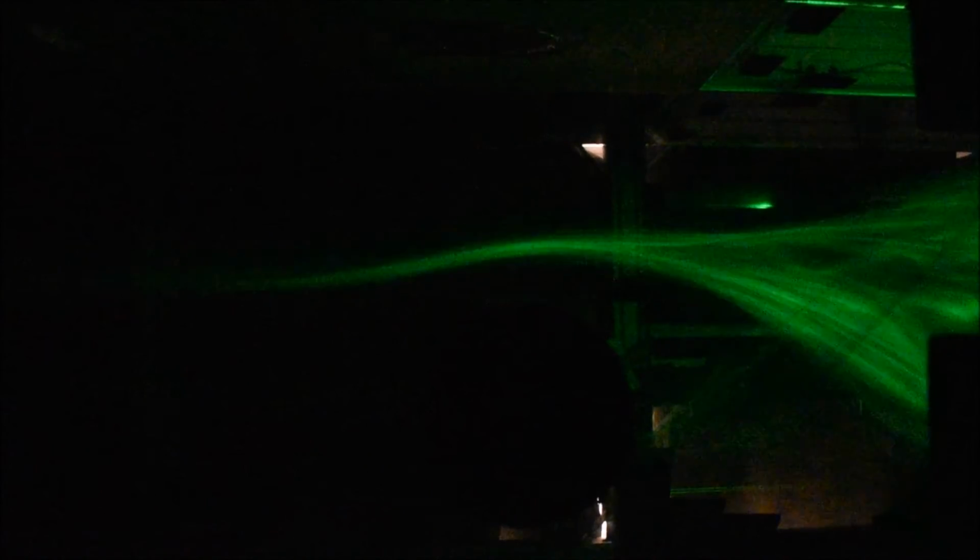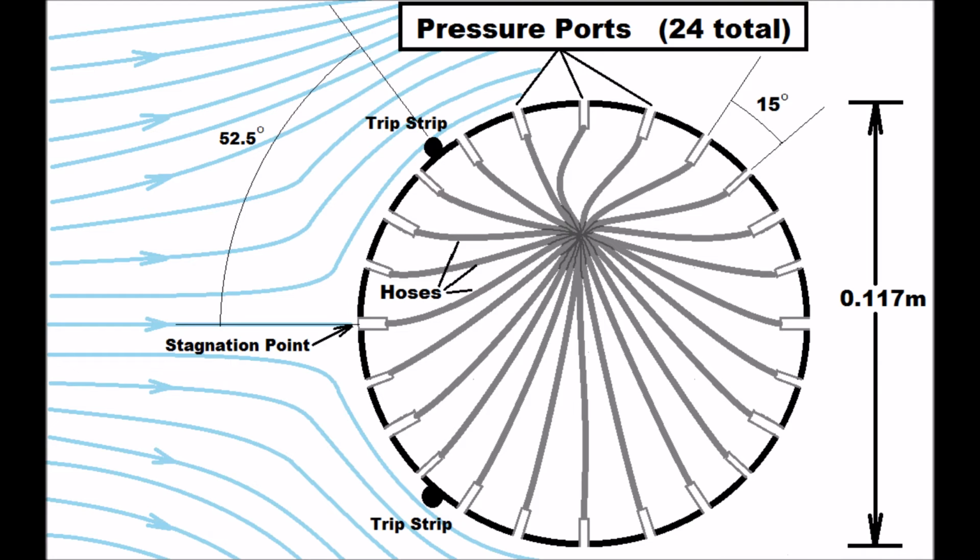Before we collected any data, we set LabVIEW to receive 100 data points from each pressure port. The data was collected with a period of 200 and an average per frame setting of 10 and 20. Next, the ambient conditions were recorded for the wind-off data. After going through the safety checklist required before running the tunnel, the RPM was set to 300 and the tunnel was switched on. After a 20-second settling time, 3 different data sets were taken for repeatability purposes.